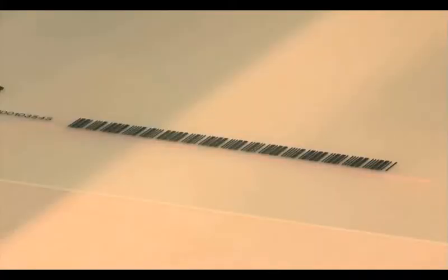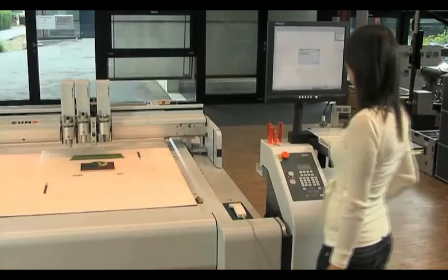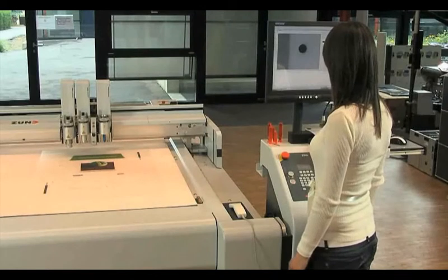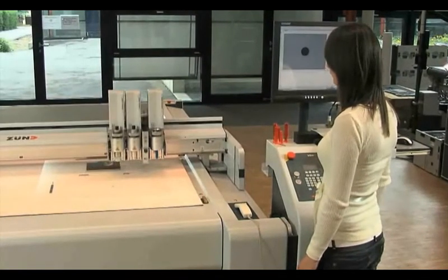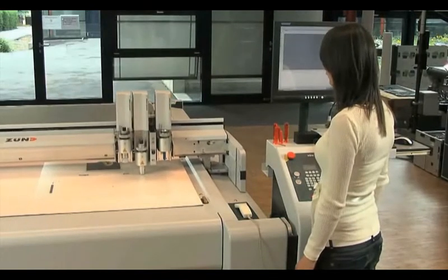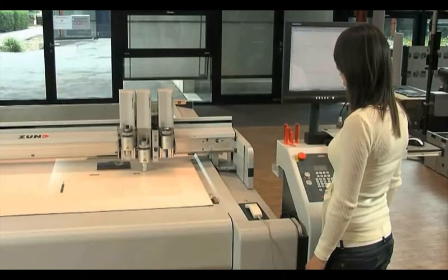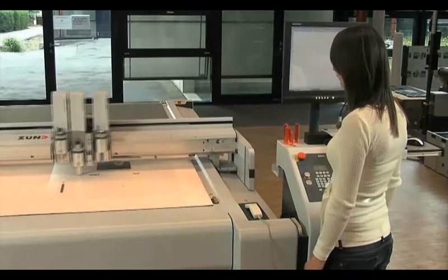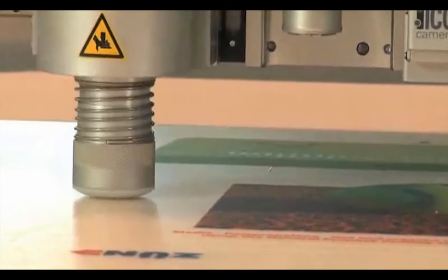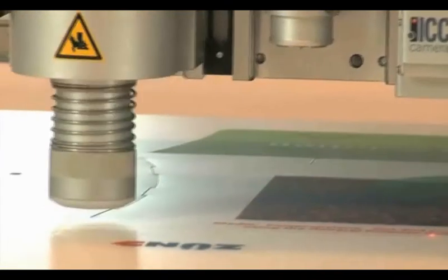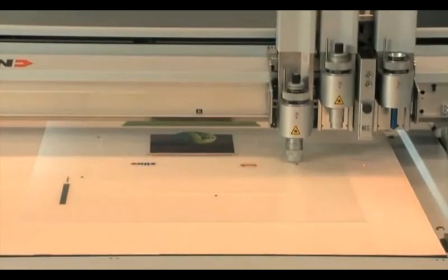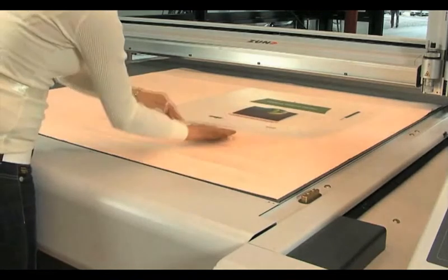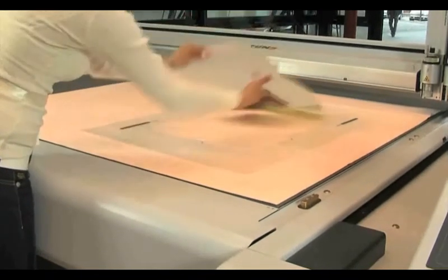SoftRip's table cutting option provides a number of features for customizing your workflow. You can add a barcode prefix of up to 2 digits, so multiple rips with multiple print units can produce unique barcodes for every print unit on every system. You can print barcodes that are stretched along one axis so they are more readable but don't require any extra space. All color names are passed to the output file, which the table cutting system can then flexibly translate into such things as changes to the cutting tool, router cutting depth, and more. These customizable tools allow you to fully automate your table cutting workflow, increase productivity, and minimize mistakes.